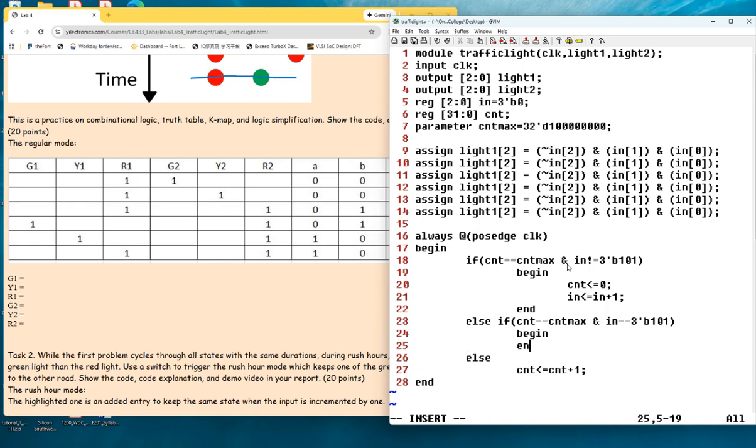You need a begin end, right? You don't need that count equals count max, do you? It has to, right? If it's not equal to count max, I need to just add a 1 to counter. Well, but else if, you could just do if n is equal to 5, then reset it immediately and reset count. I don't think you need to wait for your counter to go up. I think it would be the same output no matter what, right?